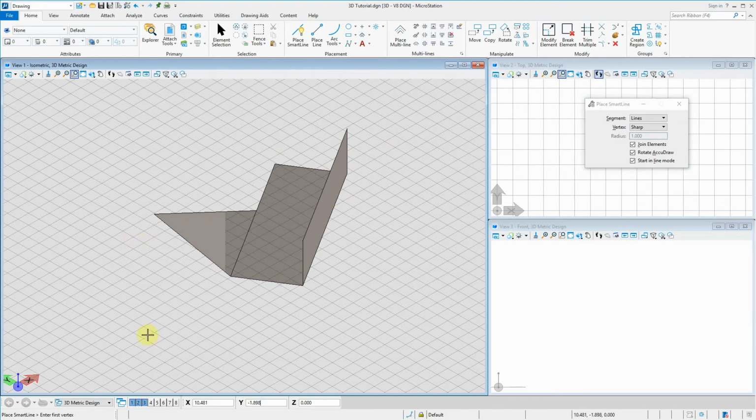So you can have your original direction, your origin here, your XY, which you can change if your building is arranged in a specific way. Generally, what you would do is arrange this towards the true north of your site, if you want to be drawing like that, or towards a side of your building that's more prevalent, so the orientation of the building. But sometimes, you might have shapes that are irregular and don't follow a strict 90 degrees angle. So that's where you would use the RE command to change the orientation.